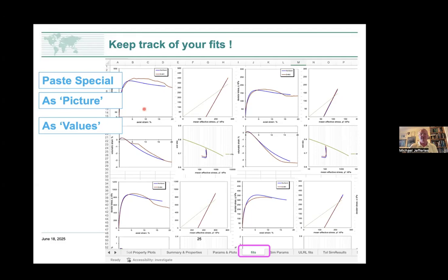Today we're replacing old-fashioned calculation files with Excel workbooks, but that doesn't change the fact that a review engineer should be able to pick up your workbook and read it like a book. So you should put in there reference information, description of what you've done, clear graphs, and in Excel, you can happily annotate things. If you've got an uncertainty and a reason for a particular choice, describe it in the spreadsheet.